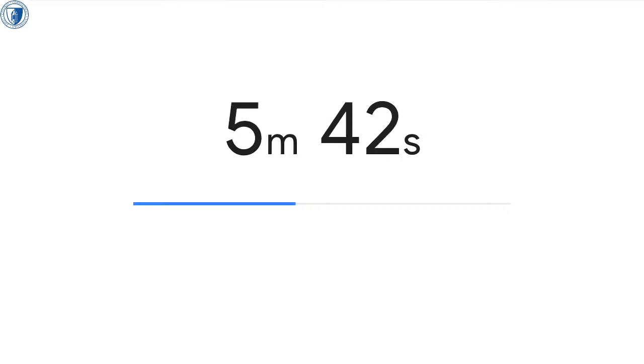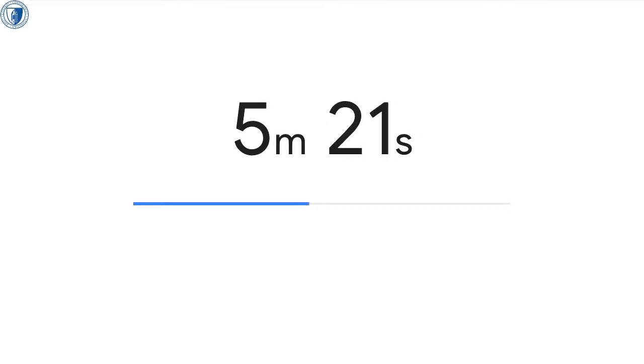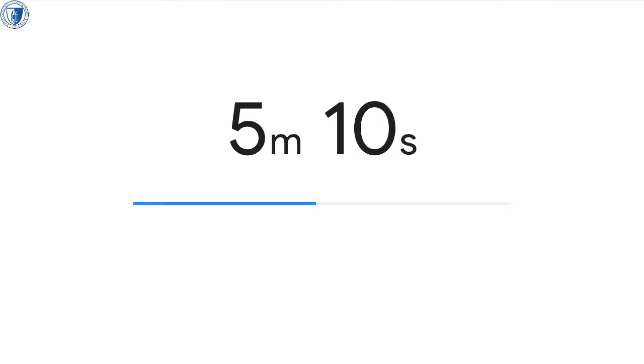Okay, now Quartus has a few megafunctions that you can use, and we're going to use one of those to let you design your own counter with whatever inputs or outputs you like. I'm not sure what that is. I'm going to hit yes. Now, this is our LPM counter, and you'll see that there are quite a few fewer options than when it first came up because we're not really using any of those fancy things. All we want to do is divide by 50 million. So we're going to need an input,